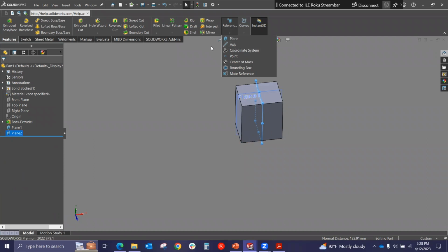selecting axes, and sometimes the hole geometry, as you all know, when you import step files and stuff, they're almost never really holes. They're like two semicircles. So a lot of times what I'll do is, if I remember offhand, I'll sketch on a circle, and then get my axes, because otherwise it